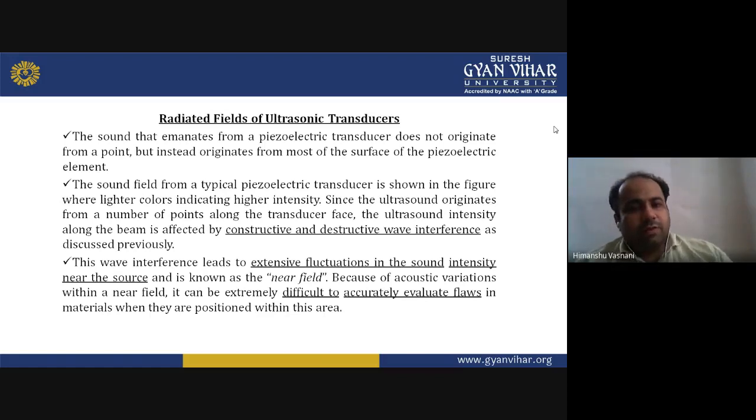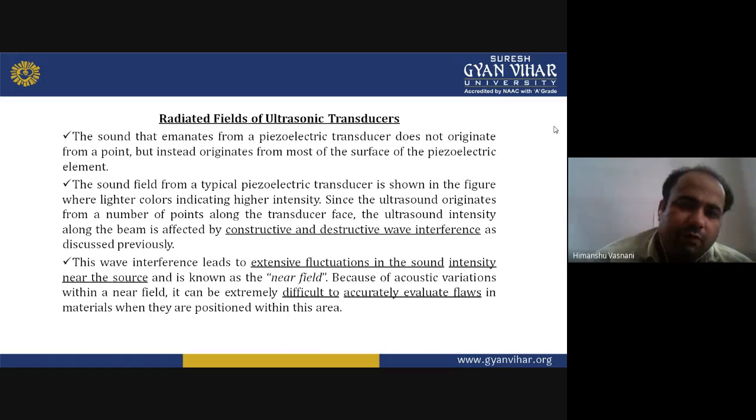When you have extensive fluctuation in the sound intensity near the source, during that near field, because of acoustic variation, the evaluation of flaws or finding of discontinuity is difficult. You can say the accuracy gets hammered. It is difficult to find out in materials when they are positioned within this area, so we have to be careful with that.